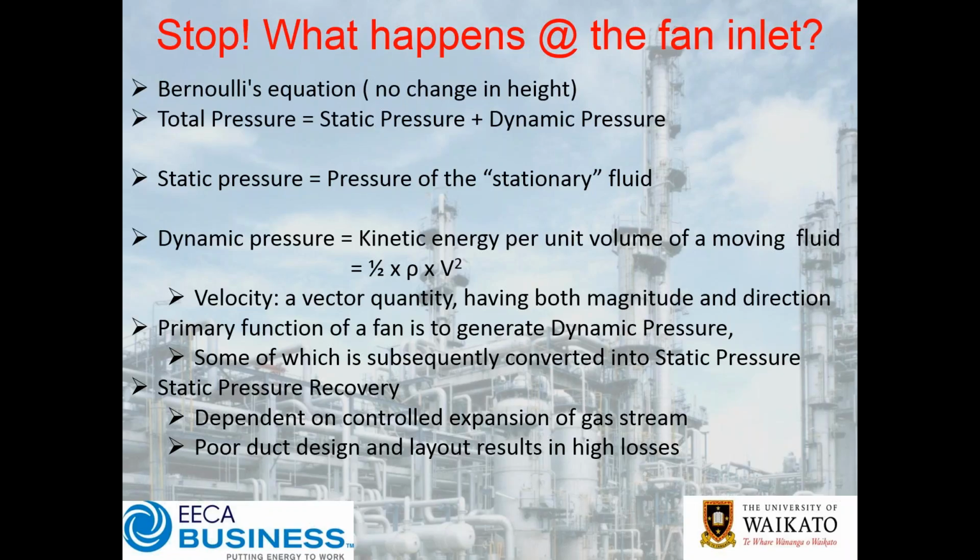Remembering, of course, that velocity is a vector quantity having both a magnitude and direction, and in ducts we'll have an axial component plus an in-plane component. So if we have x as our axial direction, our y and z in-plane components will contribute to the magnitude of our velocity and therefore the energy in the flow, but not necessarily to the actual volumetric flow rate, because the volumetric flow rate is the axial velocity times the area.